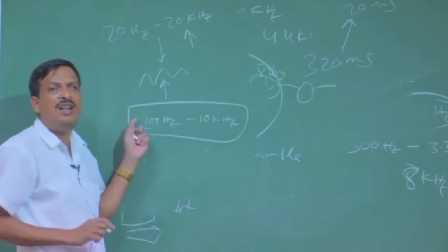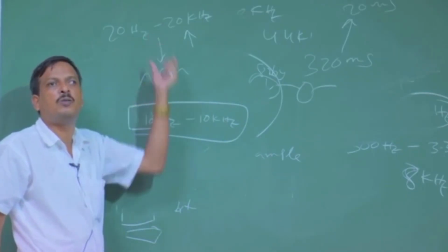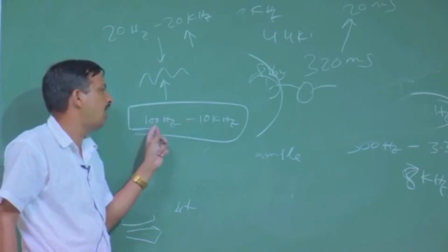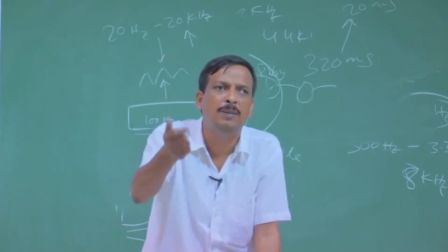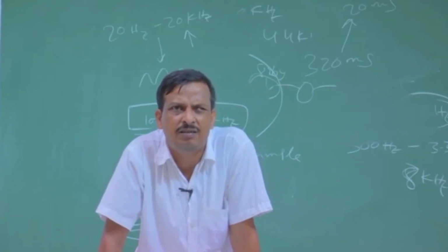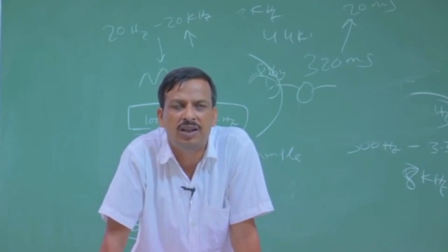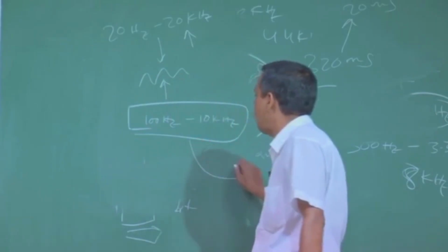It can only transfer the acoustic wave to an electrical signal in the range of 100 hertz to 10 kilohertz. So, if I apply a 12 kilohertz acoustic wave, it may not produce any signal. So, I am not getting any information in the electrical wave. Once I get that electrical signal, I will pass it through the digital card.